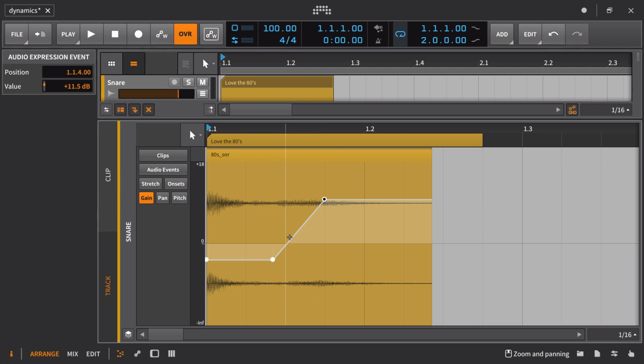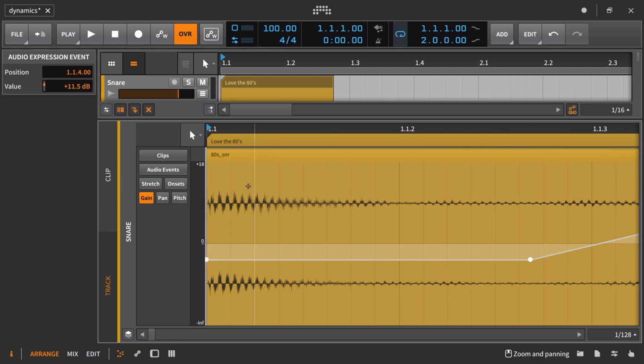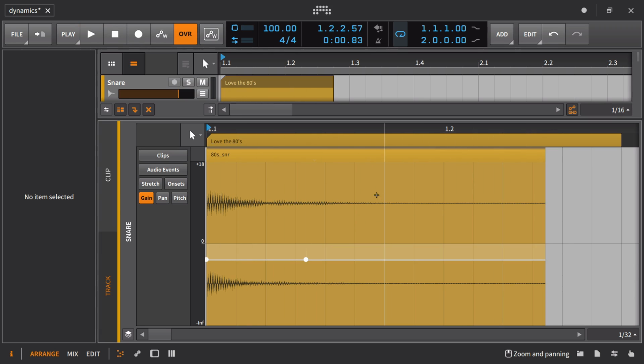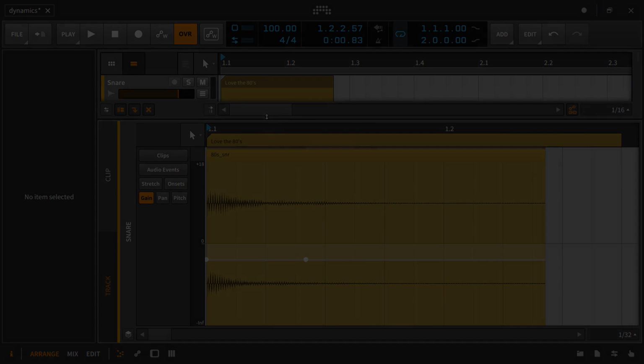And so this is an inverse of what you have with downwards compression, where when the signal is too loud, it turns things down. And that, of course, reduces dynamic range. The same thing can be said about upwards compression depending on how you set it up. So we could have a threshold point like around here and immediately jack this signal up. And so it almost levels this out. Less peak energy and the perceived loudness is going to increase. But this is the general idea with upwards compression. And so we'll try to emulate this sort of sound using a couple of different effects that are capable of doing this.